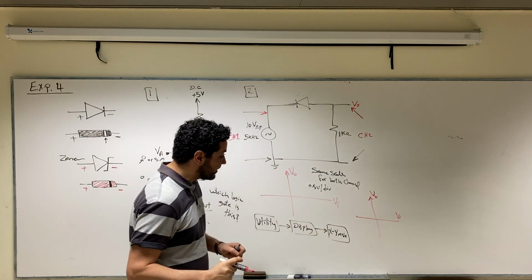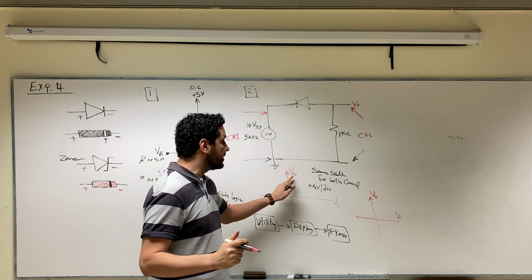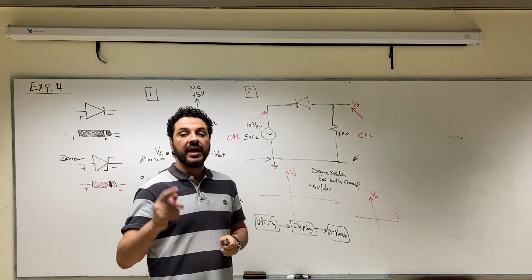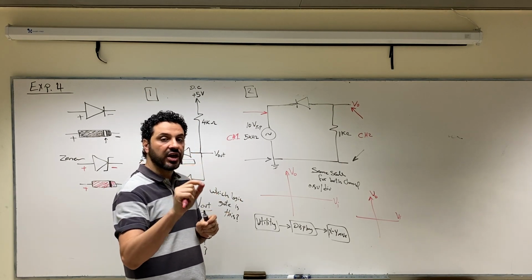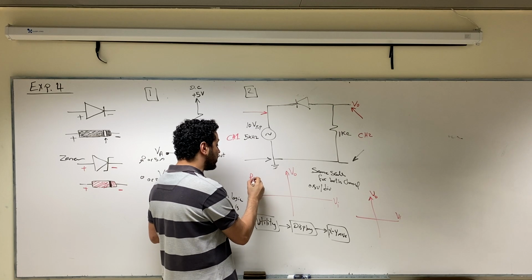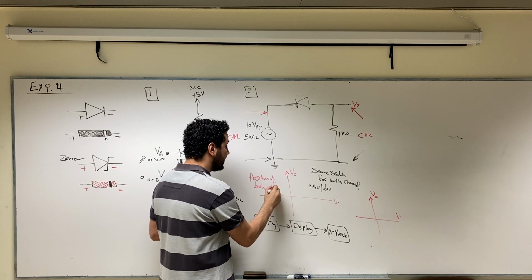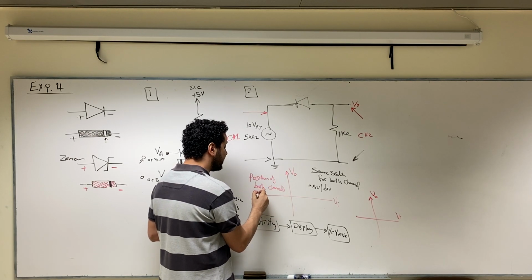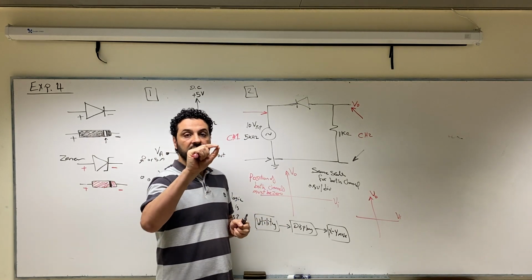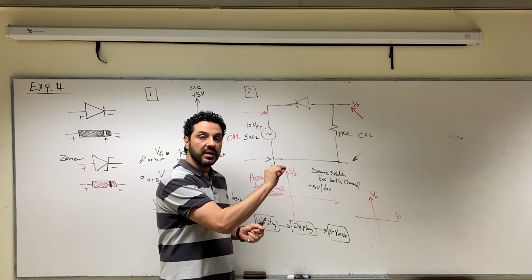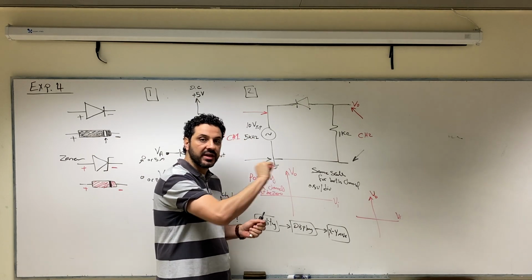One more thing about the XY mode is that we need to set the same scale for V output and V input, and additionally you need to set the position. Use the position button of channel 1 and channel 2 and set the positions to 0. Position of both channels must be set to 0. You can do that by changing the position button until you see 0 appear on the oscilloscope for channel 1, and then you change the position of channel 2 until you see 0.